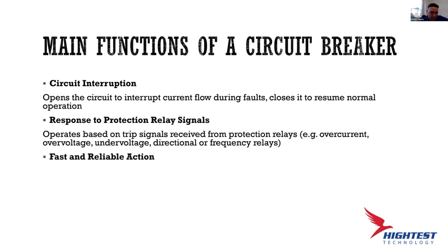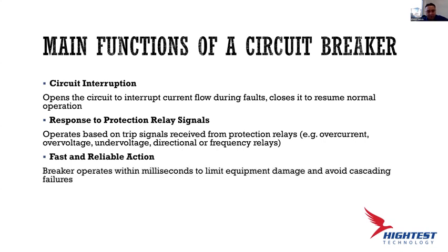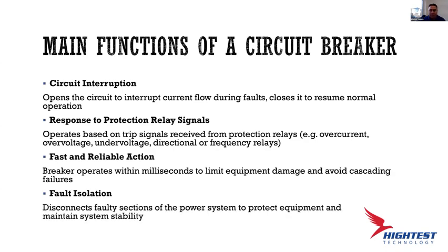To be honest, in a simple way, it is fast and reliable action. The breaker operates within milliseconds to limit equipment damage and avoid cascading failures. And fault isolation disconnects faulty sections of the power system to protect equipment and maintain system stability.